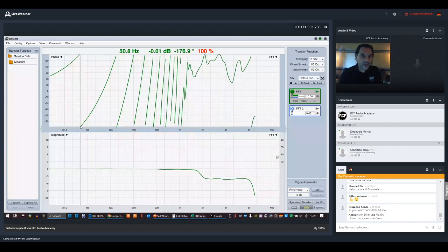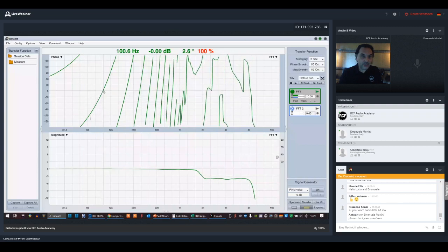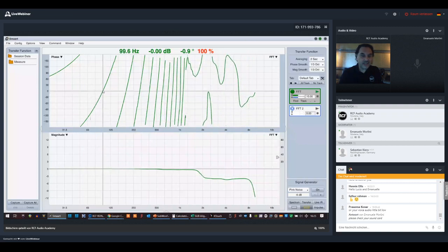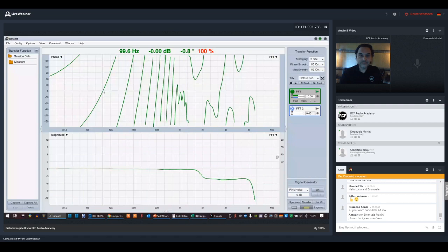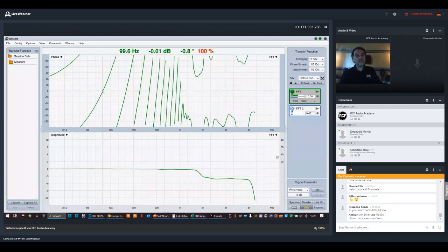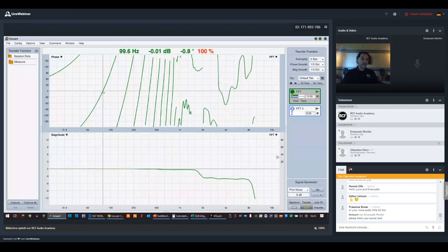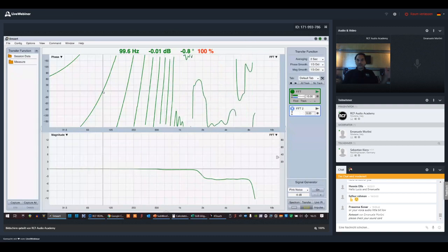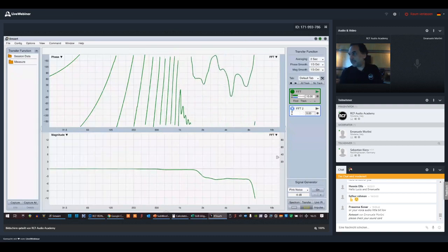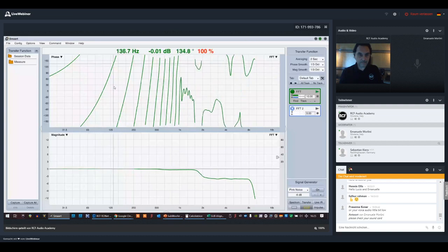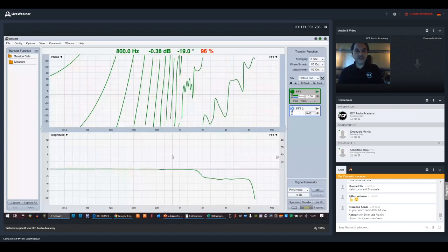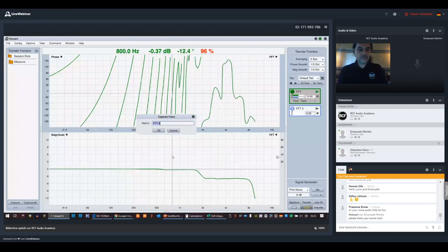In fact, you see that the first point at which we are intersecting 0 degrees of phase shift is 100 hertz. Because this means that before arriving here, that frequency will travel for one cycle, for one period. So let me capture this measure with the name 10 millisecond.